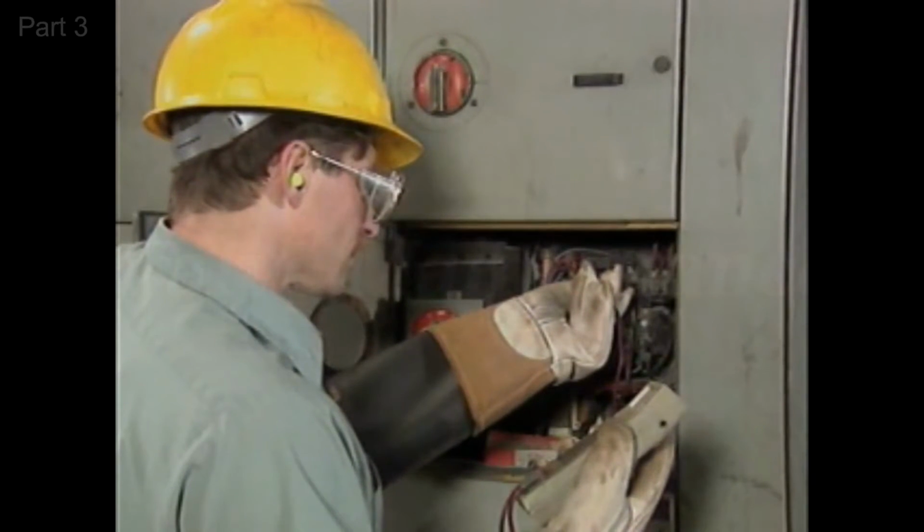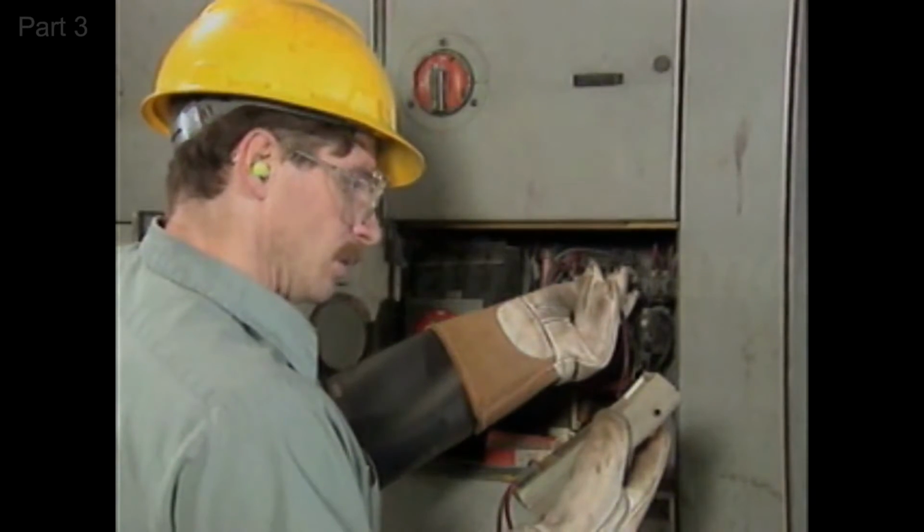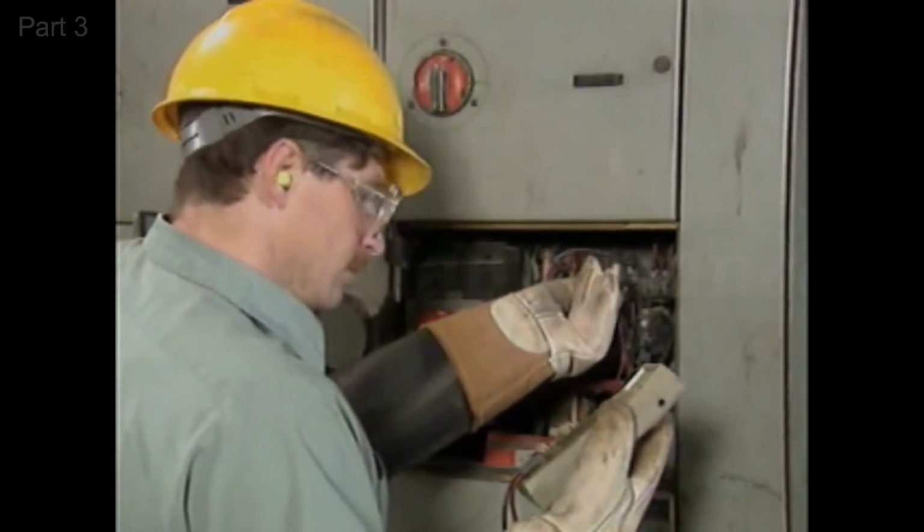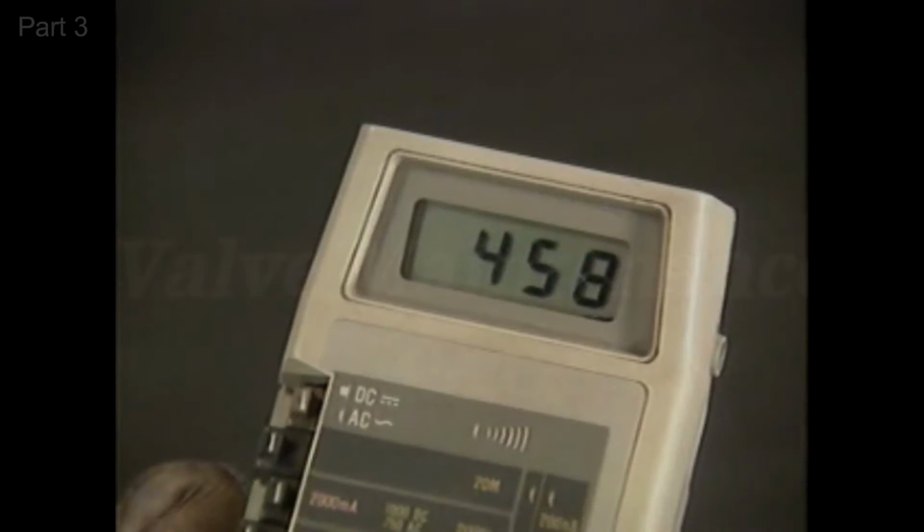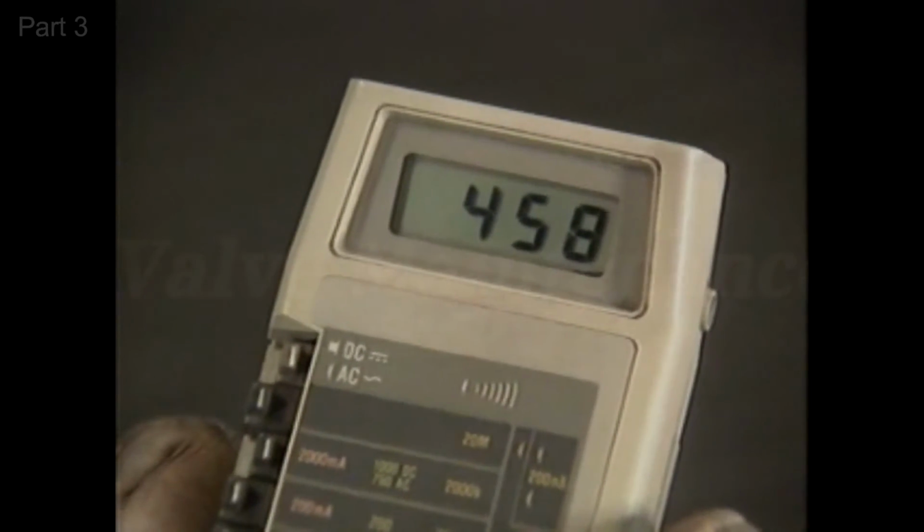When a short occurs, the controller's fuses or circuit breaker open and the controller is de-energized. For this reason, energized controllers are not normally tested for grounds and shorts, but they are tested for opens. One way to test an energized controller for opens is to test for voltage drops across various parts of the controller's circuits. Generally, if an open exists in a circuit, there will be a voltage drop in that part of the circuit.